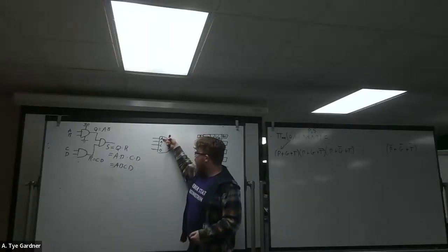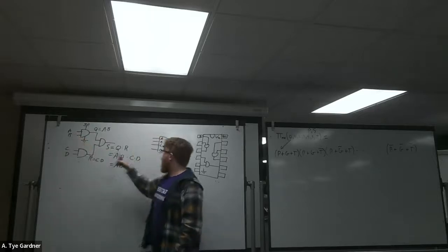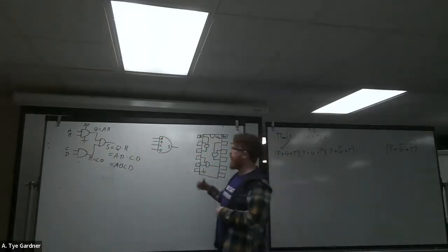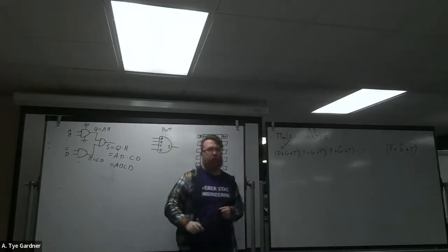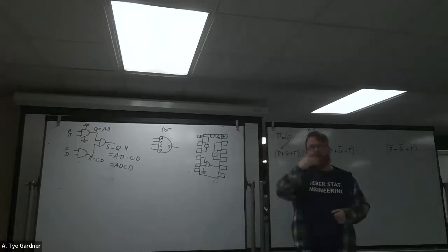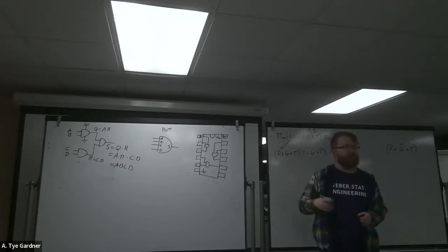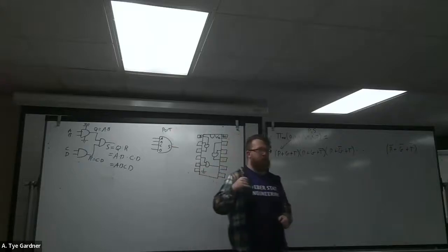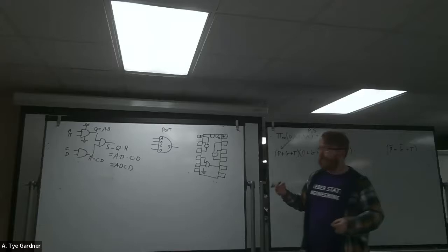Similarly, these guys, this A is this signal A, okay? But to the outside world, this guy's not a signal. He's inside the package. He is what's called a port. Okay, it's a port. And so these ports are how I access these blocks. I haven't really used much in the way of ports, right? Normally I just call it a signal and I plug it in and I'll let you guys make the assumption. But these ports are really important because they're going to come around and bite you in the butt if we don't understand them now. But I'd like you to understand how we're building these things as blocks, okay?